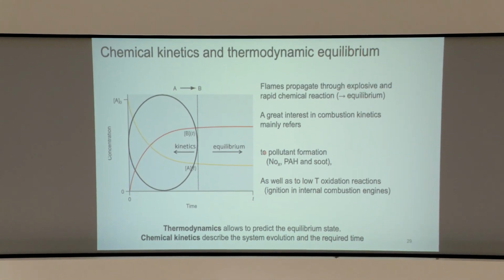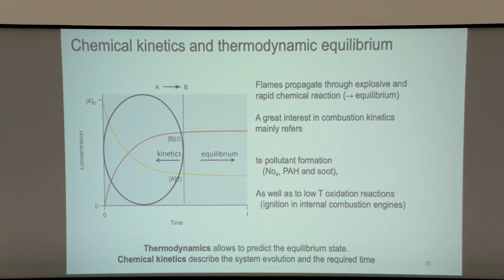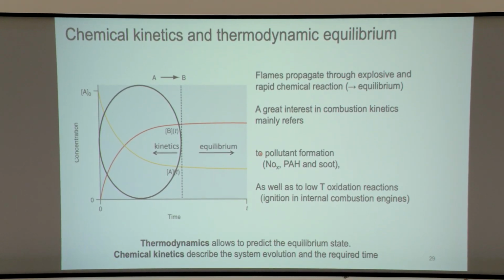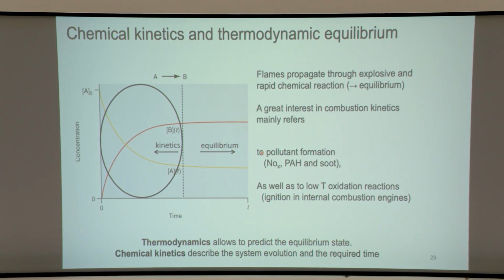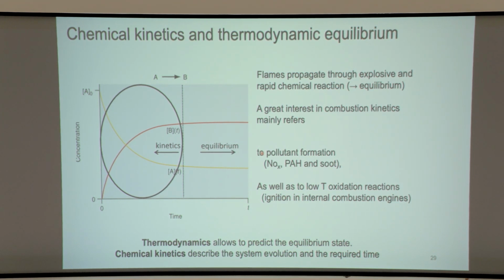In a combustor, though, we're typically going to high pressure because you have fuel plus oxygen and you want to favor the formation of products, CO2 and water. If the water condenses out, CO2 is the main gas, then you typically want to go to high pressure. You can get better reactivity. You also get faster reaction rates at high pressure. So all of that is to determine the equilibrium state of your system, okay?